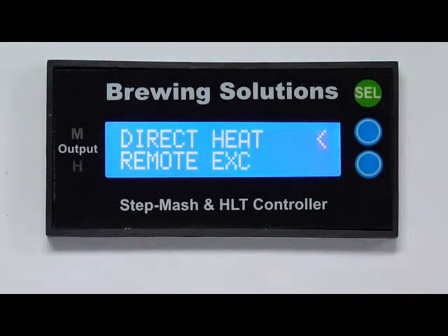Directly heated systems will typically have a much shorter dead time than heat exchange systems. For improved accuracy for dead time determination, two different routines are used. Use the blue buttons to move the cursor to either the direct heat for directly heated system or to the remote exchange for heat exchange systems. I will select the direct heat for my heating configuration and proceed.